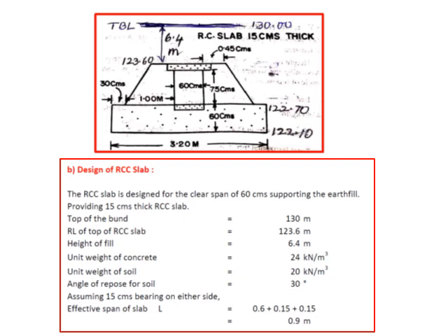We have provided a 60 centimeters thick concrete bed. You know that the sill of the barrel is kept at the canal bed level, which is 122.7. So keeping 75 centimeters and providing an RCC slab 0.15 thick, we get this RL as 123.6.